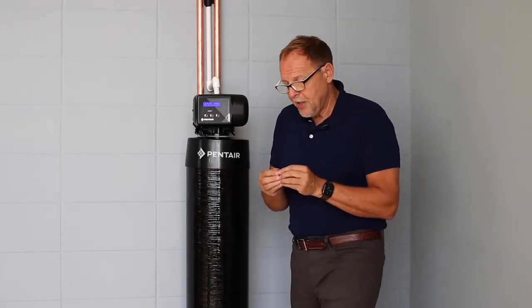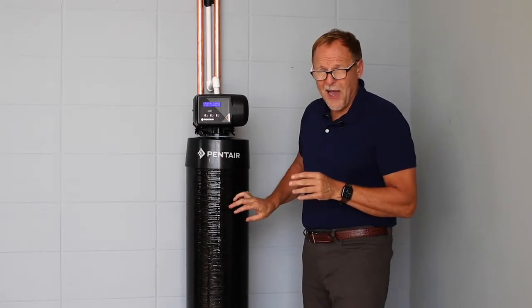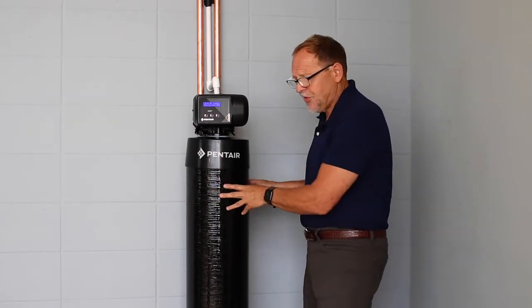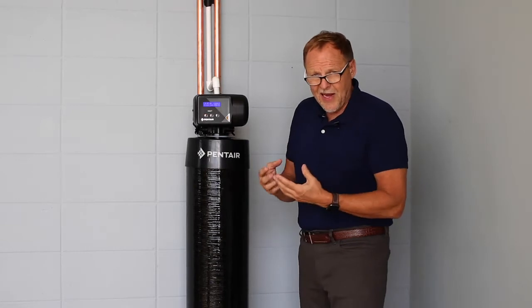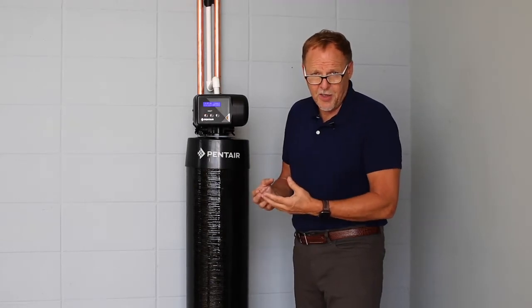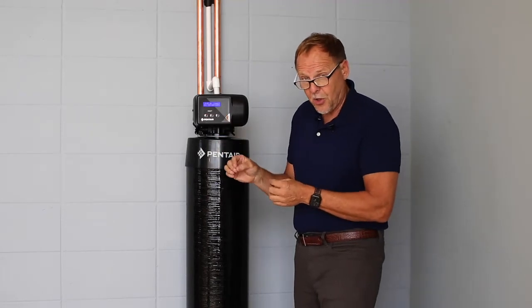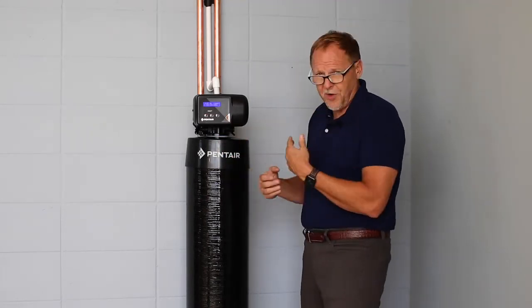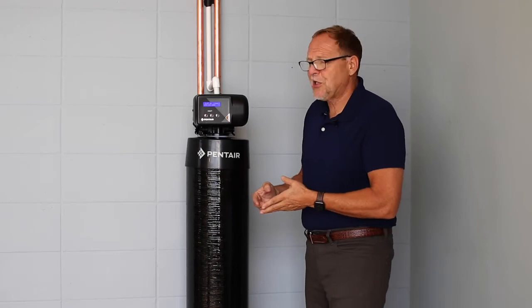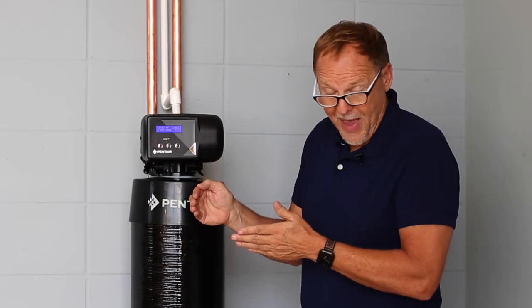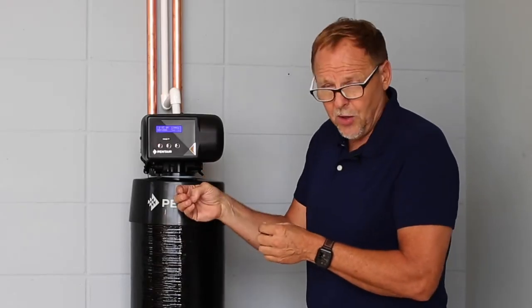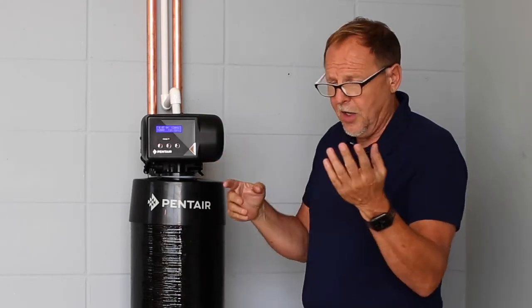But keep in mind, all backwashing filters, carbon, neutralizers, and so on, the mineral is very light until it gets water saturated. So I don't want to test the backwash cycle on a brand new startup. I want to let the water run for 24 hours. So during my startup, I'm going to quickly go past the backwash cycle into the rinse cycle and then go on from there, and I'll show you how.